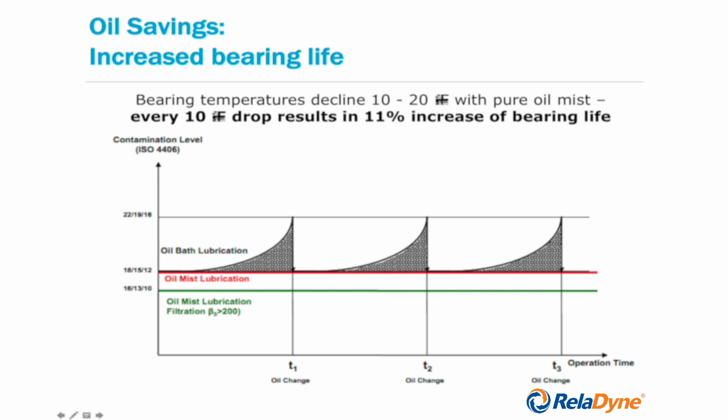Well, if we have conventional lubrication, we have to change the oil after a time that we have labeled on the horizontal scale as T sub 1, because we have now an increased concentration of debris, the oil has gotten hot, and as a result, as a precaution, preventive maintenance with that kind of lubrication, the traditional lubrication, one changes the oil at time T1.